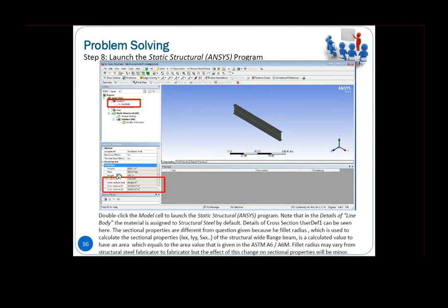You can check its mass, its length, as well as its cross sections. The I here refers to Iy and Iz. It's a little bit different here: 510 and 15.3, so we have 513 and 15.352. So that is the closest, but of course you can fine tune it to get as close as possible. Probably because of the radius of the fillets, the curve itself.